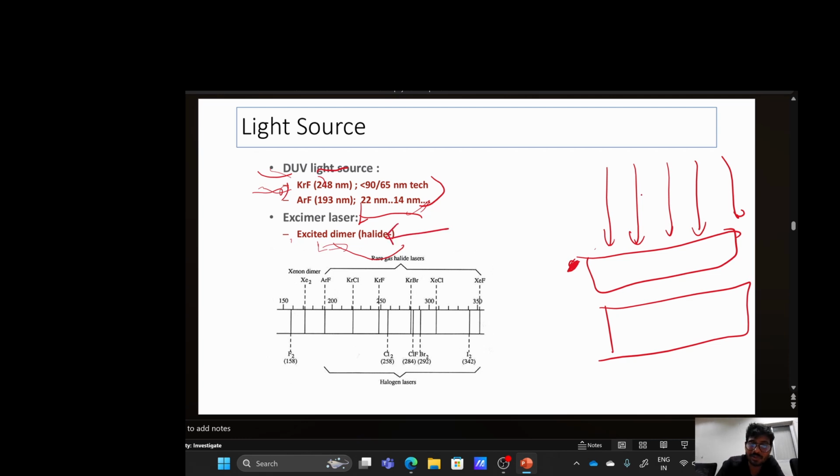With lasers you can write pixel by pixel, but with the light source you can write within seconds. Projection lithography can be done with these light sources only, not with excimer lasers. For lower feature sizes you can use lasers, maybe for research purposes, but not for industrial purposes.